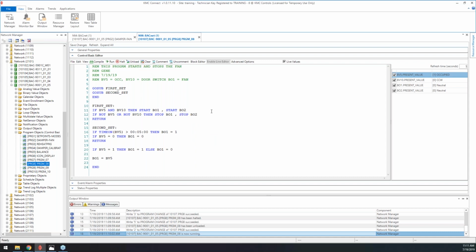Right. Then if you want to make a comment at the end of that line, you need a colon, because a colon indicates that this is a new line. And you can simply write then the REM statement, and there has to be a space after REM. You can't start typing unless there's a space there, which you see Gene doing. So it's the REM and then a space. That's all part of the REM statement. The controller will not execute anything starting with a REM. So it stops executing that line when it sees REM, and it goes to the next line.